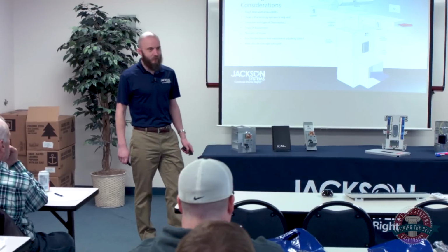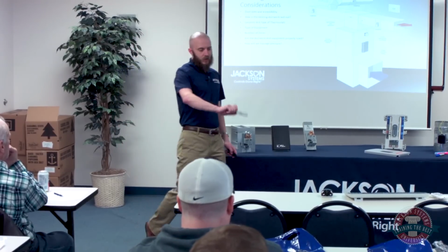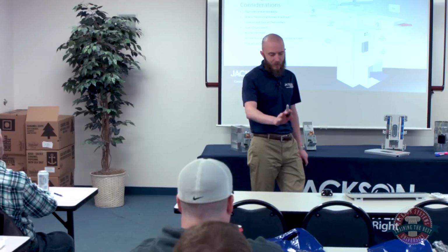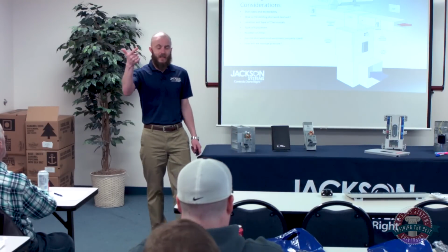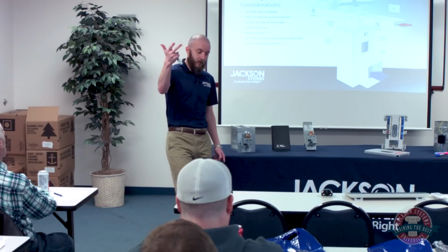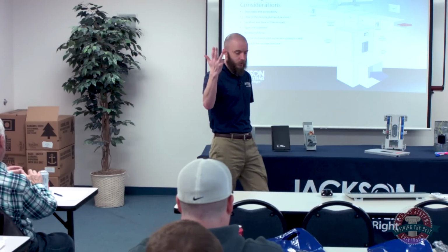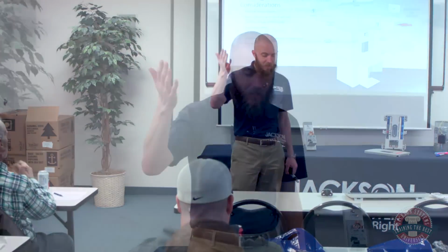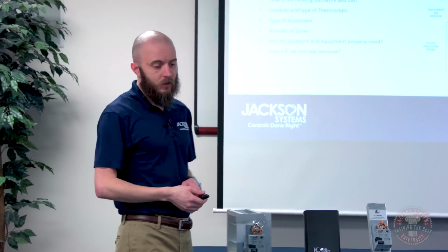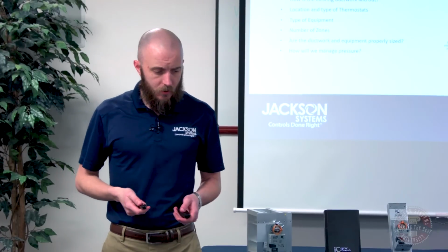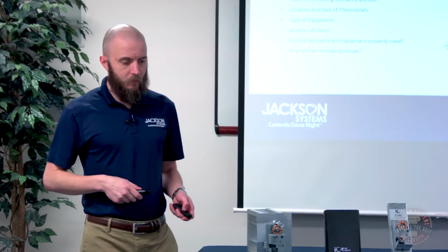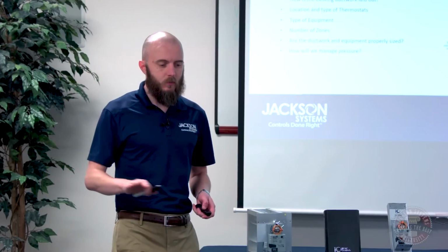All right, so moving on from there. The components here are primarily the components you're going to need for a zoning system. You're going to need thermostats, dampers, a zone control panel, a discharge air sensor, some method of static pressure control, and I don't show it on here, but we always recommend installing a separate transformer for the zone system. I'll talk about that in a second, but that helps with troubleshooting and helps alleviate a lot of issues that pop up from time to time.